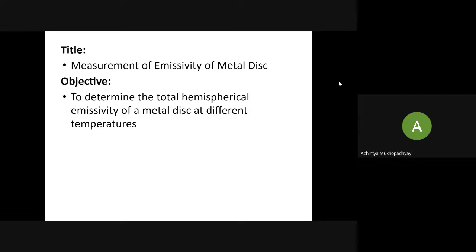And finally, when we are considering all possible directions and all possible wavelengths, then we have neither the superscript, nor the prime, nor the subscript lambda, and that epsilon is a function of temperature only. I mean, for a given material, and that is what we are measuring here. That is what we mostly use.